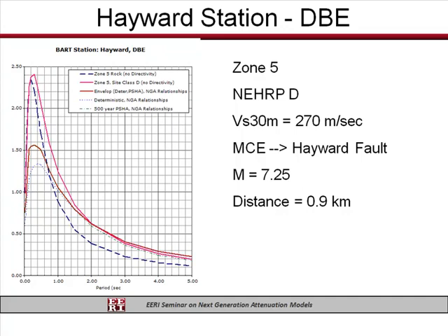But basically what I'm going to show here to start off with is 5 curves. The first 2 listed in the legend are the thicker blue dashed line, and on top of that is the pink line. Those are from the 2002 study. So the blue dashed line is what you get for the reference rock conditions, assuming the conservatism, but adopting that that's applicable to a VS30 of 760 meters per second.